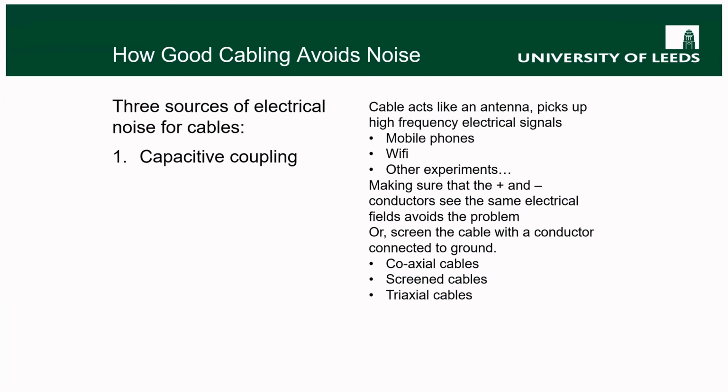What happens is that the inner and outer connections of the cable will pick up that high frequency signal from the environment, and they'll see it as a voltage. You're essentially charging the cable as though it's a capacitor.